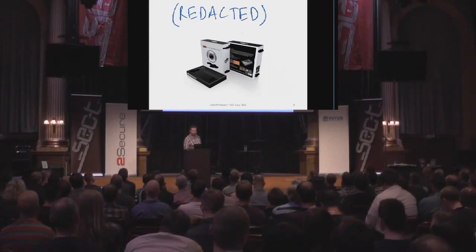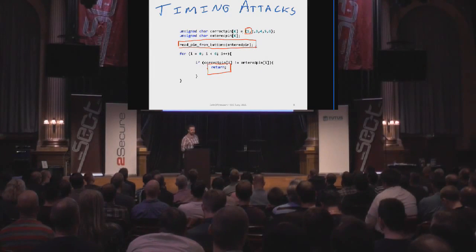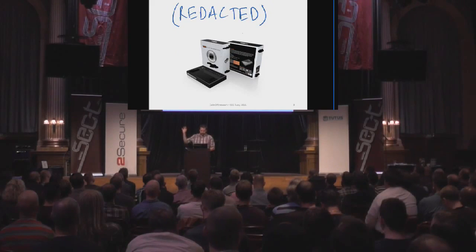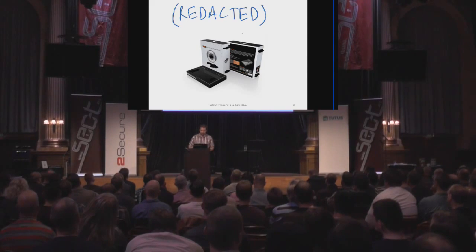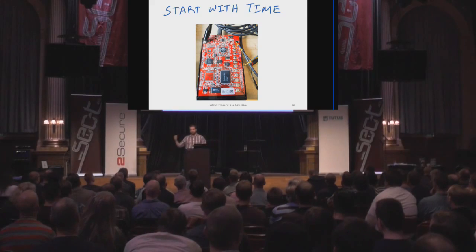People put up these slides and you go, well, no one really does that, surely. So as an example, this was a crappy password-protected hard drive. It never claimed to encrypt the data. All it did was mangle the partition table. When you put in the right pin, it unmangled the partition table so Windows could see it. It never claimed to have encryption, but it did say, if you don't put in the pin, it's useless. They did that mangling so that if you remove the drive from this enclosure and plug it into your computer, it also wouldn't appear. So it wasn't completely terrible, but it had this really basic timing attack.